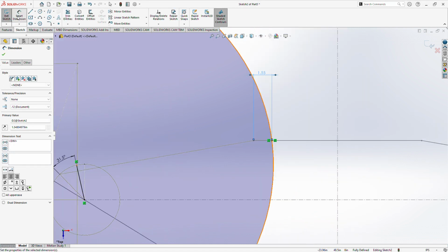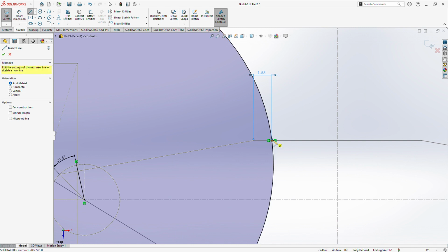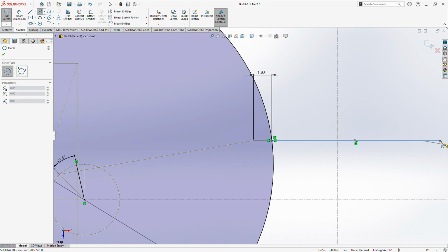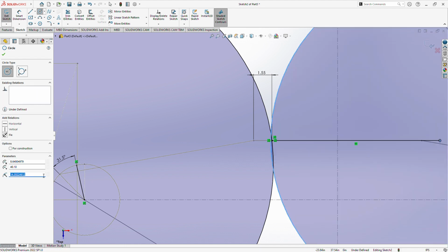Okay, we'll make the rack, when turning the rack will shift to the right, 14.2. Again take a circle, make the locus of the tie rod. The length of the tie rod is this 16.637.